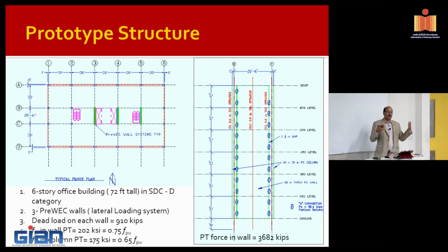So we talked about rocking, right? I touched on this last week. When a structure rocks, it bounces on the foundation and bounces back again. It goes to the foundation with a certain velocity, goes through a certain angular velocity, and bounces back with a slower angular velocity. Every time it hits something, it loses energy, so the impact damping will also be there.